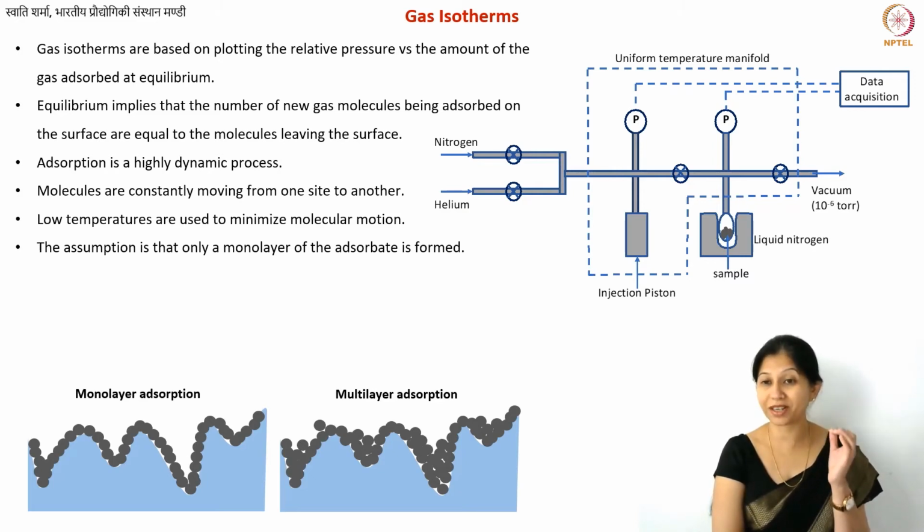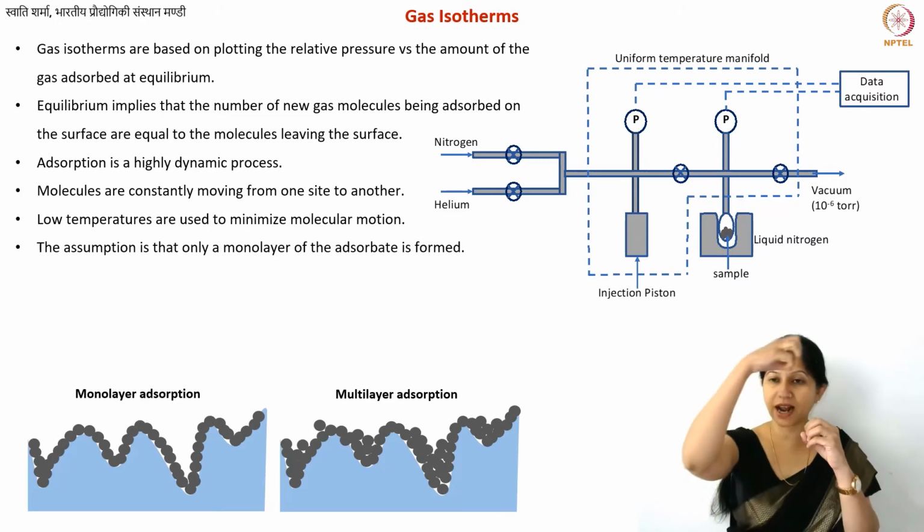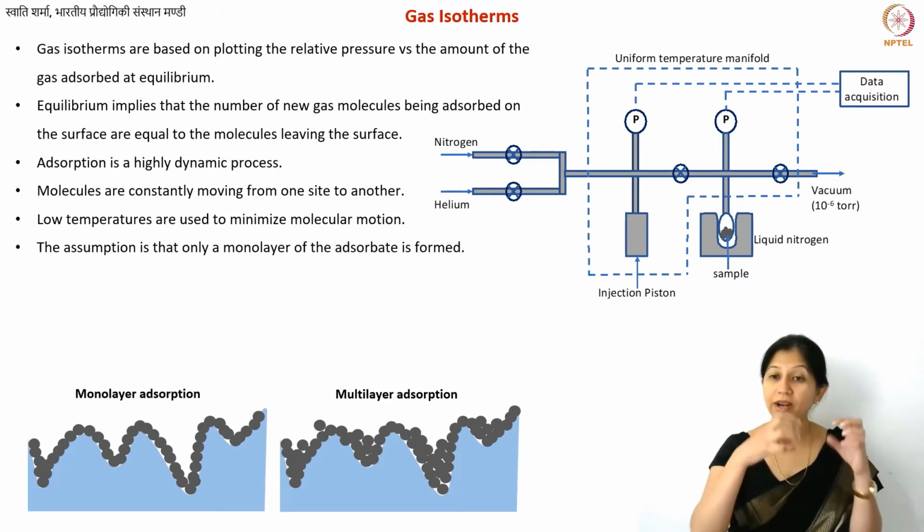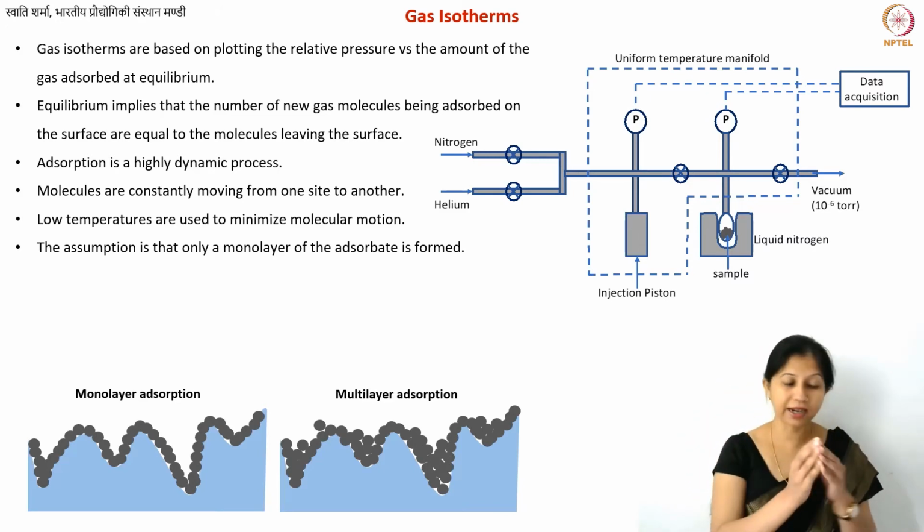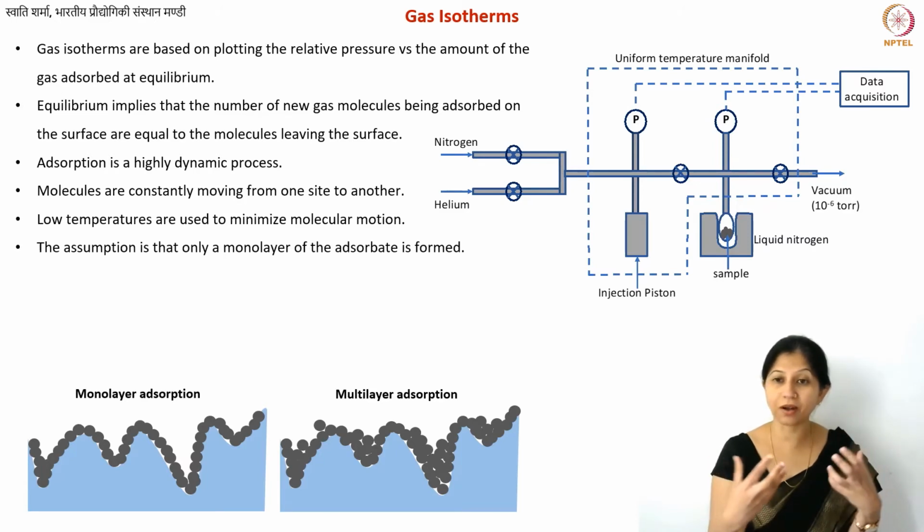But this may not always be the case, because you will often have multi-layer adsorption. Your gas molecules are also interacting with other gas molecules, and with the carbon molecules and the surface functional groups. There are multiple molecular interactions going on, and that is why you will often have multi-layer formation. But we assume that this is monolayer adsorption.